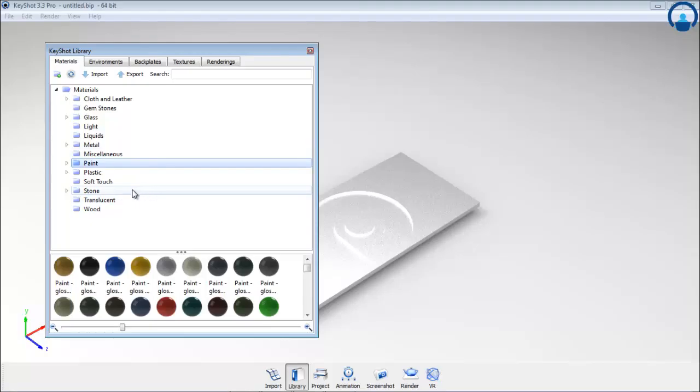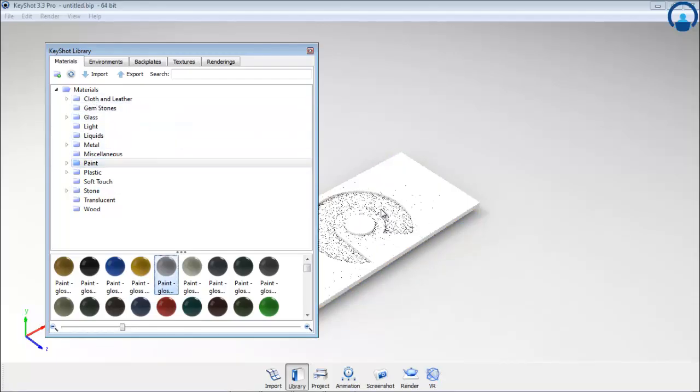You can begin with raw data, but to speed up workflow, you can apply shaders to the group or layers of material in your CAD application. Either way, applying materials to your object or model is as easy as dragging and dropping materials to your object or part of object. Hovering the material over a part will show you the preview. Simply release the mouse button to assign.